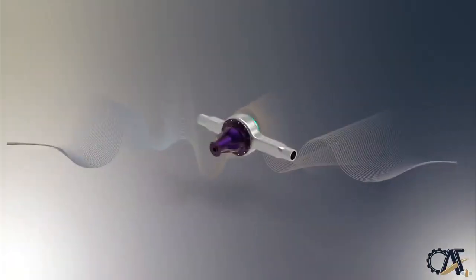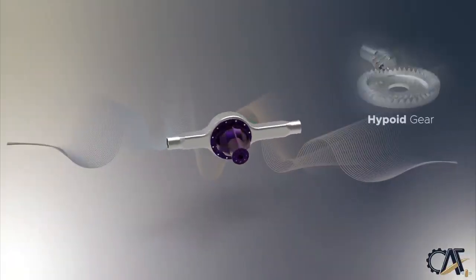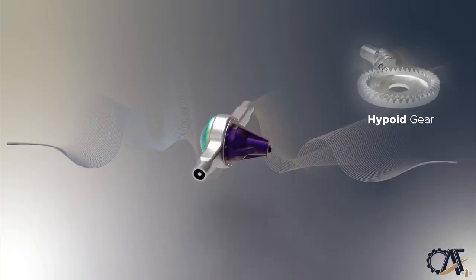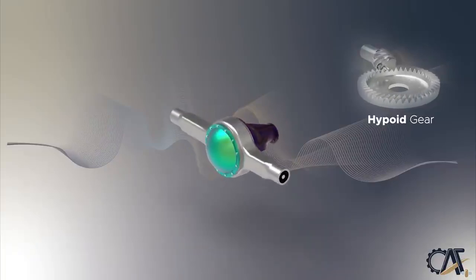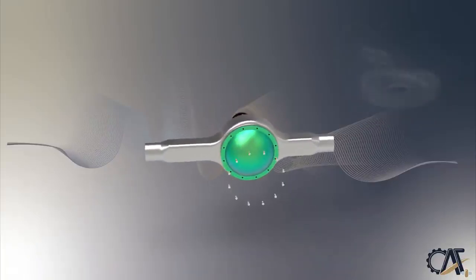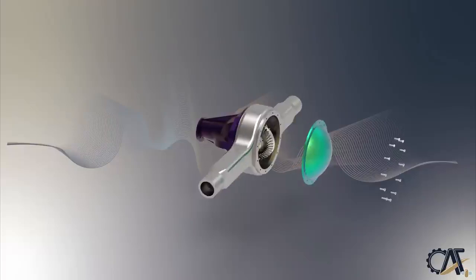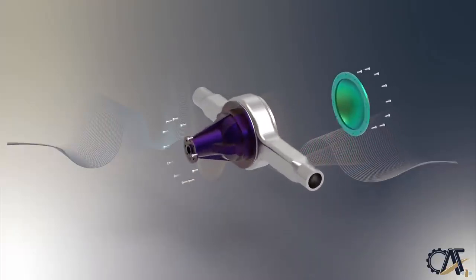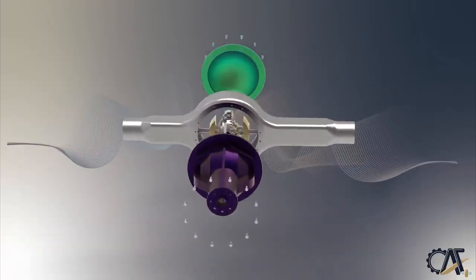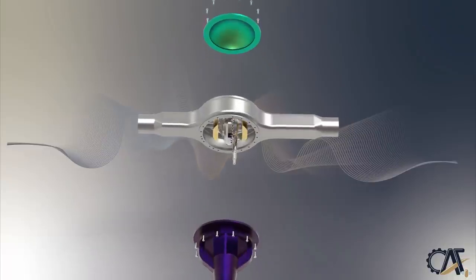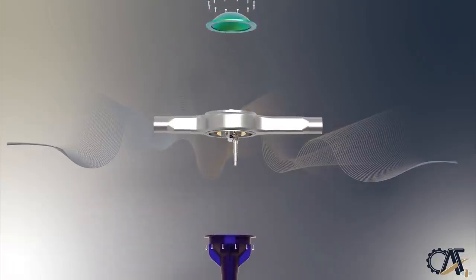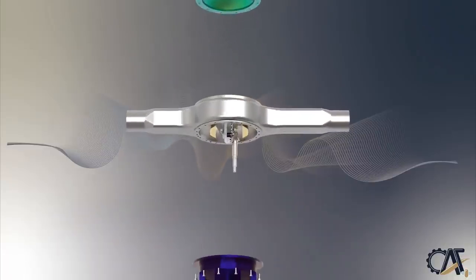Next, we have the hypoid gear, which is generally used in the rear drive axle of trucks. The rear drive axle is located between the differential and the driving wheels and transmits power between them. As explained earlier, the hypoid gear has an offset from the spiral gear. So what is the benefit of the offset? The reason for the offset is to lower the center of gravity and avoid a bigger propeller shaft tunnel.